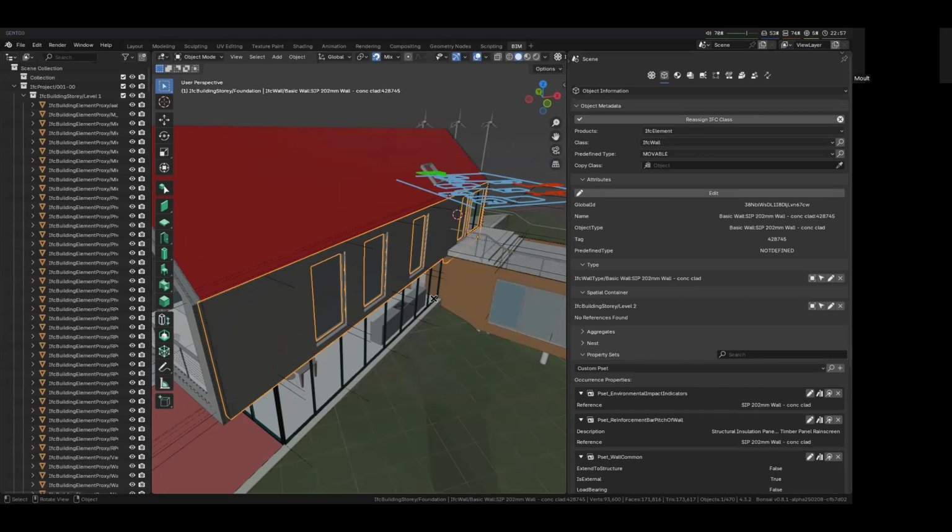The first value is that whereas your classification system might only be useful in your country or your jurisdiction, IFC classifications work internationally. And that's really nice. IFC classifications are translated, but also they are used in all sorts of other standards. For example, if you are delivering COBie for asset management, what's considered maintainable is given in terms of IFC classes. And if you want to enter any sort of data next to your objects, IFC classes are what determine what properties can or cannot be inserted on that object. So these are really big benefits.